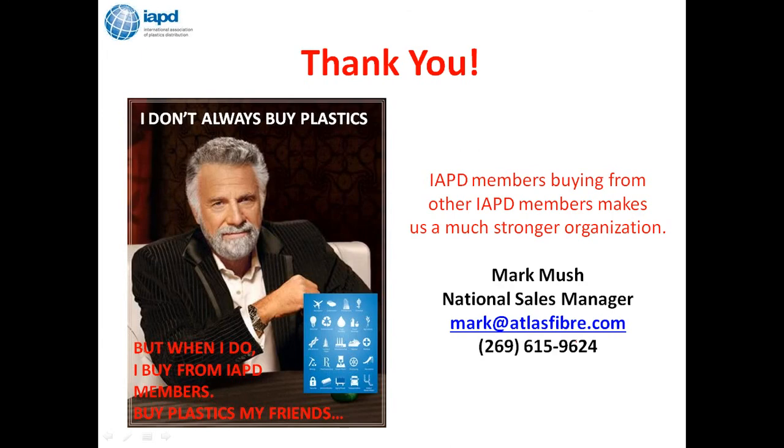We just had another question come through. People always ask for G10 material, and like you said in the past, it's automatically been given that they can use FR4 instead. What questions should be asked to clarify in case the customer really does want a true G10? I would ask if they're looking at a print and exactly what the print calls out. Is it giving you any other information as far as a NEMA grade or a military specification? That's the best way to get after it. Again, you've just got to ask the customer for more information and nail it down.